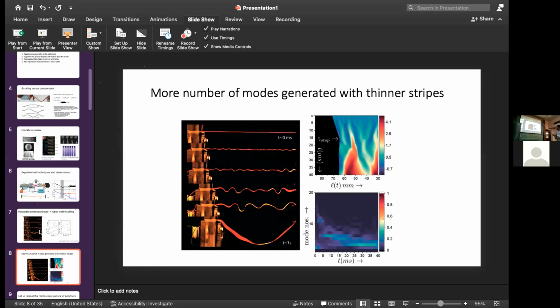So if I plot, this is my time axis. These are milliseconds. So I see this is another, thinner rubber. This is like 0.1 millimeter thin rubber. So here I'm seeing even more oscillations, and I see higher order oscillations. And this is clearly how the mode numbers are decaying from something like 12. They are going back to 1 over a finite time of 40 milliseconds.